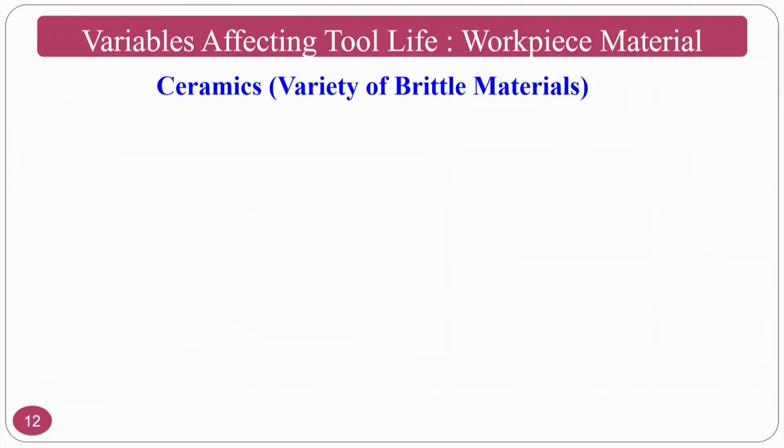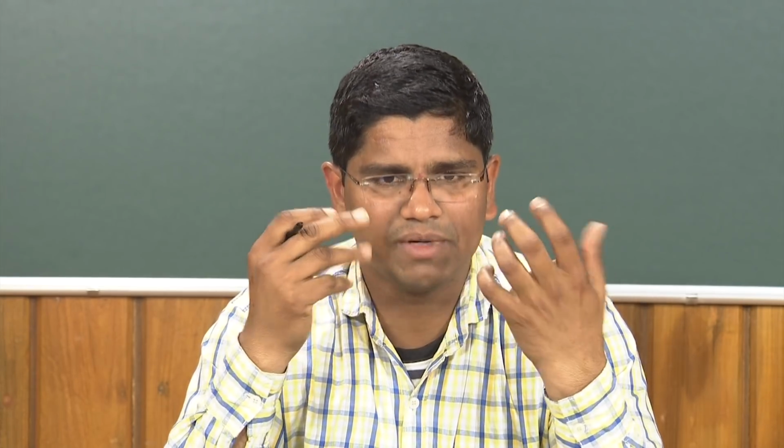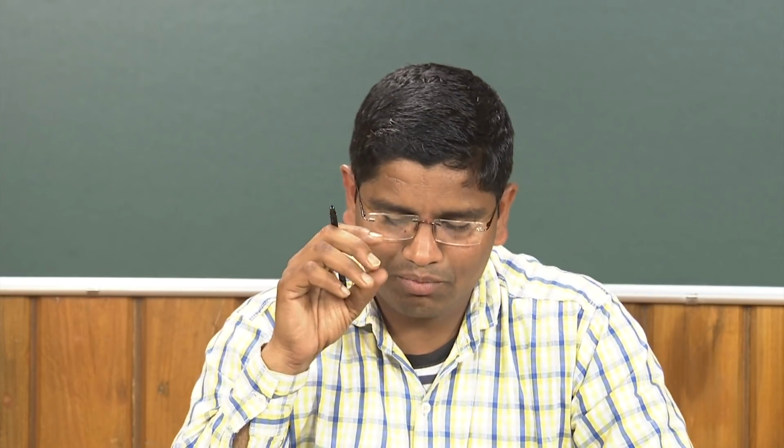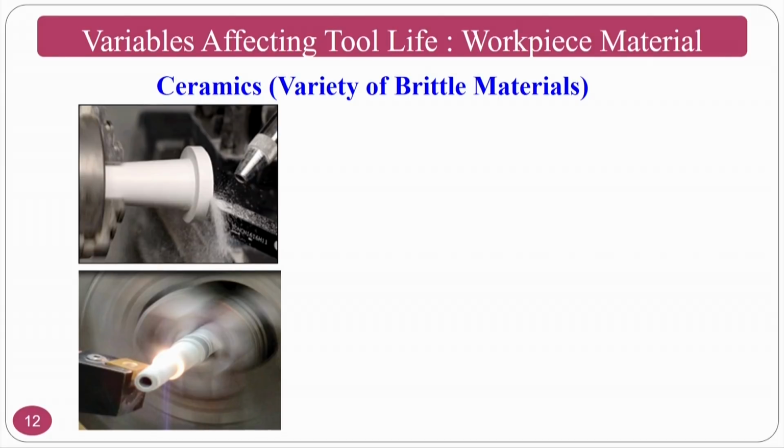Now move forward to the different materials, that is called ceramic materials. Ceramic materials can be machined, normally if it is a soft ceramic, like hardness is not that big, or if it is done by the powder metallurgy technique. Normally the ceramic components are done by the powder metallurgy technique. Whenever I want to do the machining operation of this one, you can do it by giving a low depth of cut and low feed rate and all those things. But commonly used methods are heat assisted methods. Normally if you see, these are all heat assisted techniques.